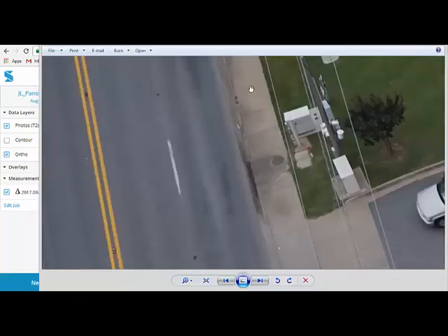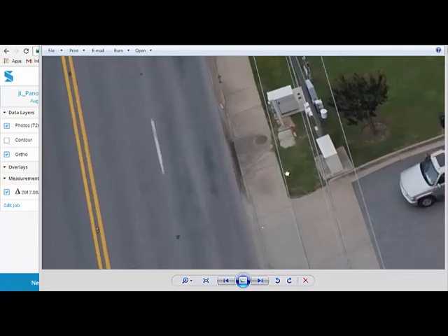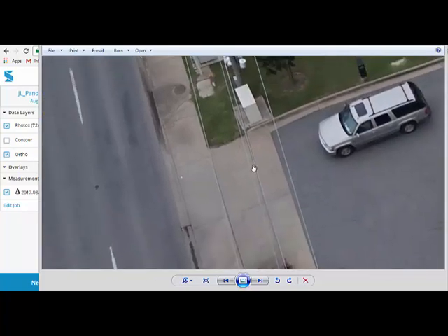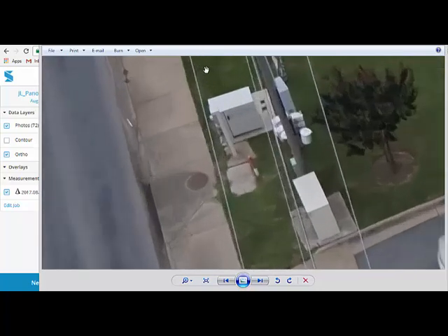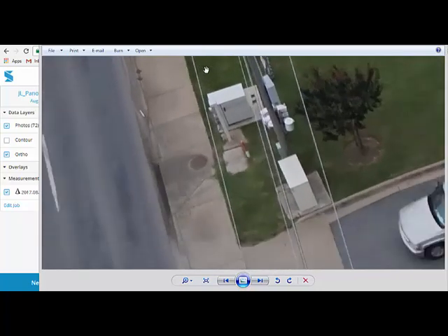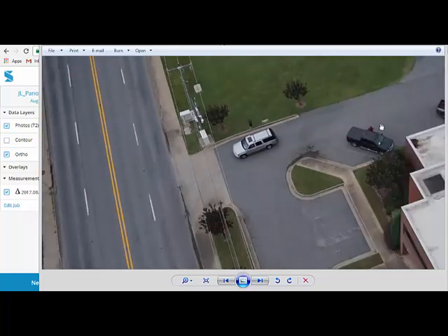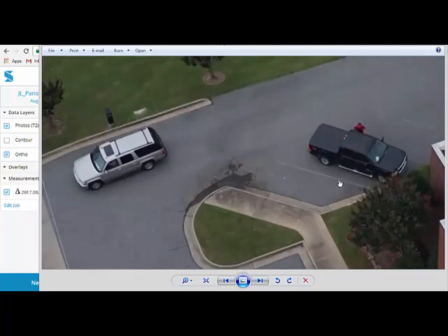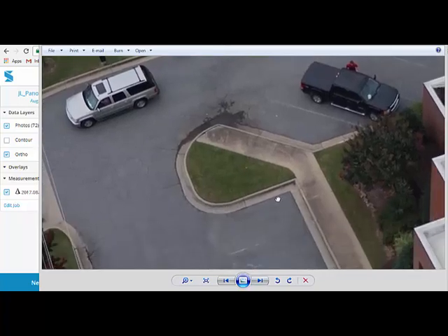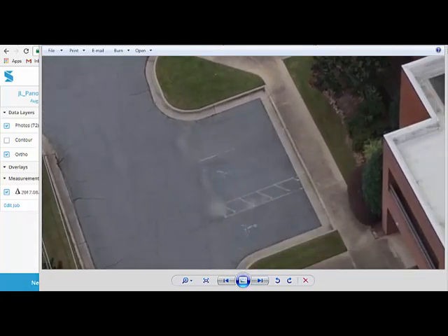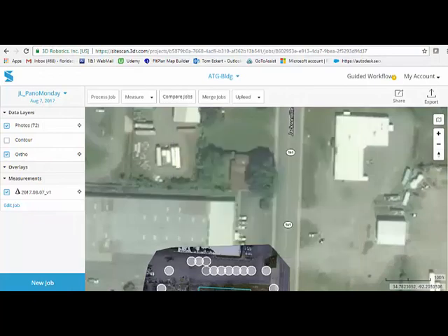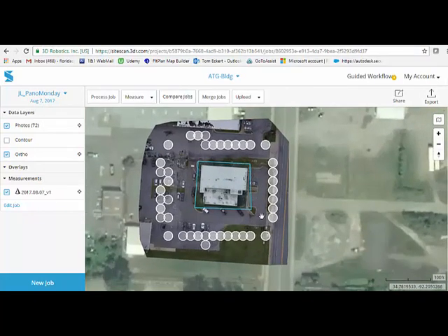So there's not the same albedo effect that you get with concrete. It is a brightness that is a too high of a reflectivity, and so shooting the site in a low light cloud cover condition actually gives you better surface data. So yes, the pictures are a little bit more grainy because of the white balance, but there is no reason that we could not just measure and find out the exact aspects of the orthomosaic once all the pictures get stitched together.